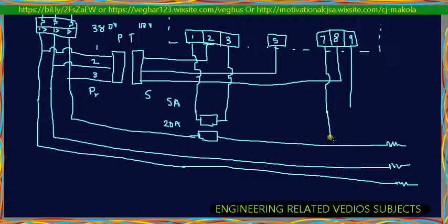Here you connect the CT on the second line. The CT helps to protect the energy meter from damage, because the supply brings more current into the system than the energy meter can carry.